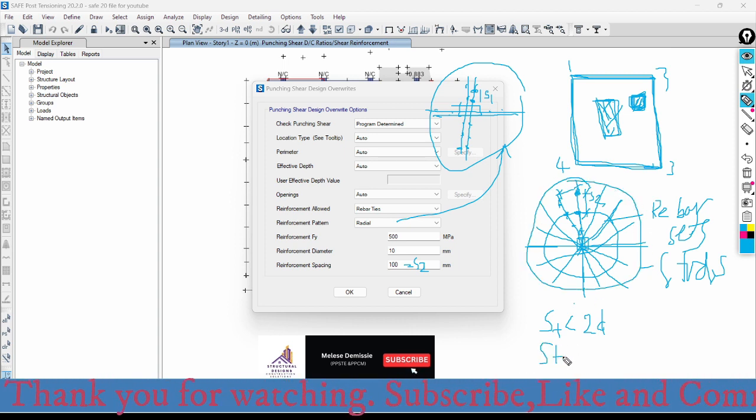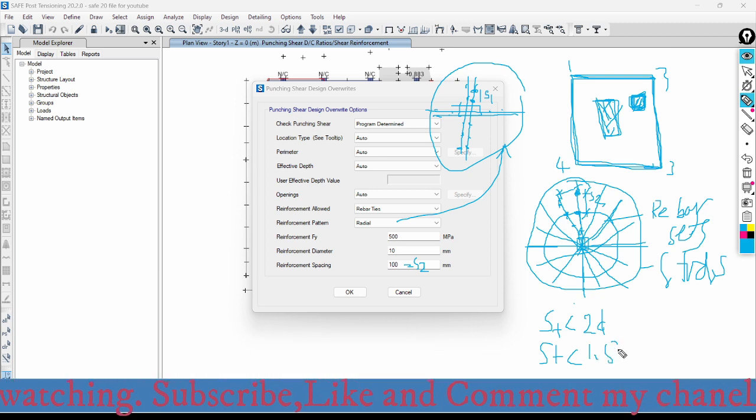And S tangential must be less than 1.5 times D within the basic parameter. That means the distance between these ties within the basic parameter should not exceed what? 1.5 D. So all those maximum limits of the reinforcement bar spacing must be verified carefully while designing the punching shears.